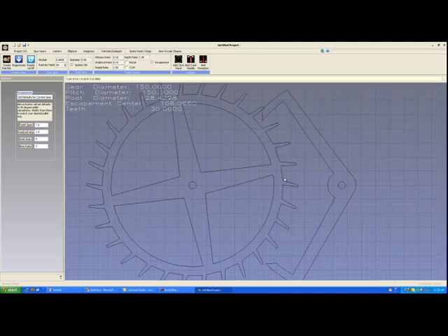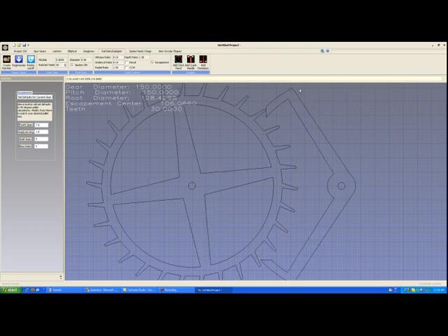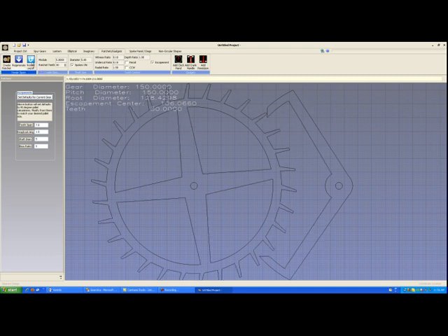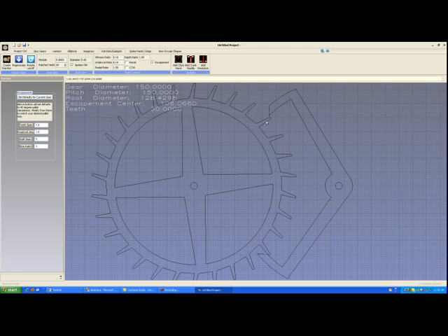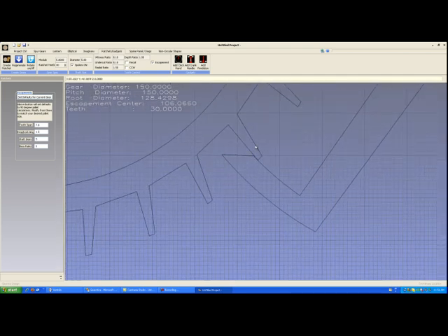The other pawl works the same way, only in a reverse orientation, because the tooth is now moving down and away from the pawl. So let's turn on the rotation. We can see now that this upper tooth is pressing on the pallet face. This is causing the pendulum to swing a little bit harder and adding energy to the pendulum. As it rotates, it will eventually flick off of the end, and when that happens, the bottom part of the pawl, you can see that the tooth has just come and is doing what it should.